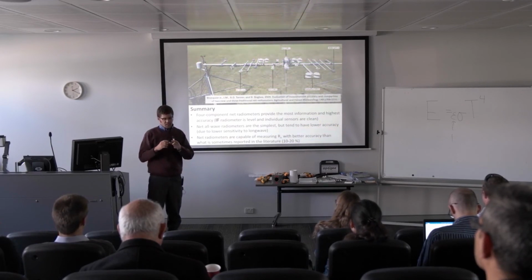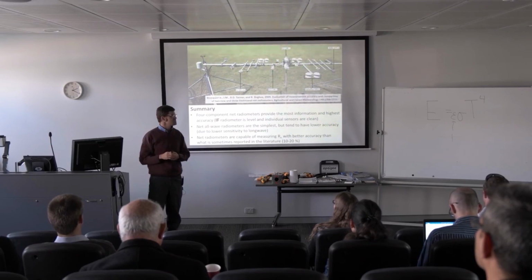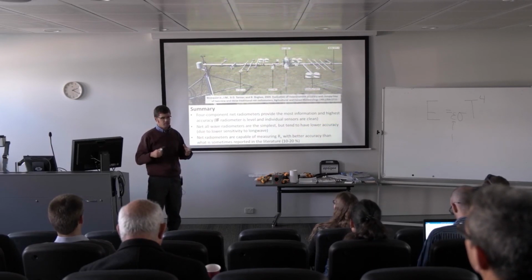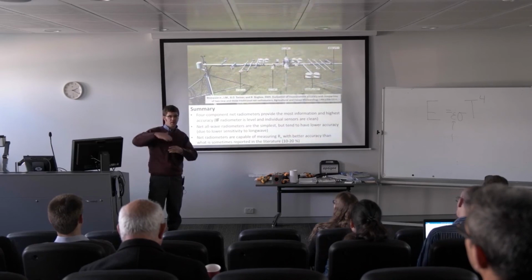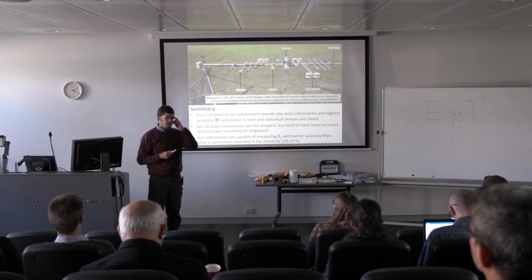And so if the near surface vapor pressure is a reasonable estimate of the whole column of water in the atmosphere, then empirically, estimating atmospheric emissivity from near-surface vapor pressure works okay. If the near-surface vapor pressure is not a good estimator of the whole column of water in the atmosphere, then the empirical equations don't work that well.